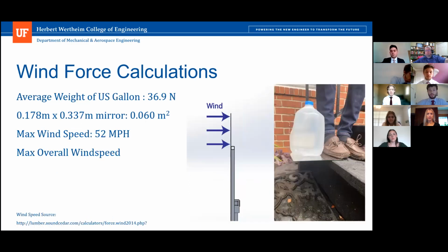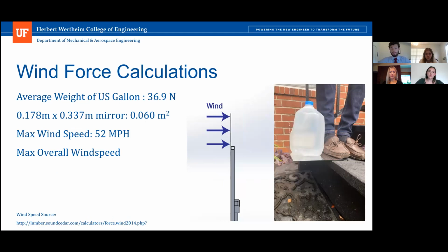Another potential failure mode that we saw was, we have a reflection surface, a mirror that's attached to a vertical welded steel or aluminum frame in an eye configuration. It's backed by adhesive. But one of the problems that we saw was a mirror overhanging the vertical part of that beam, and that could potentially snap since the glass is fragile.